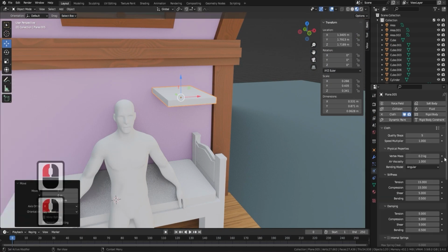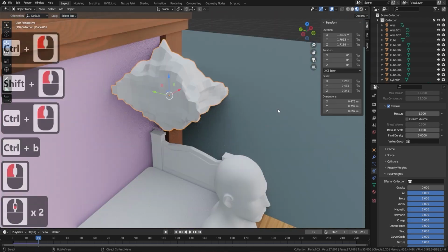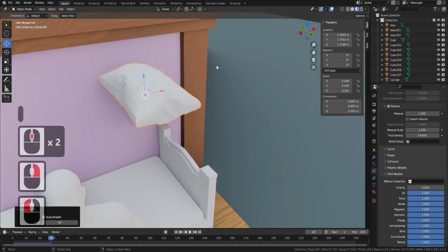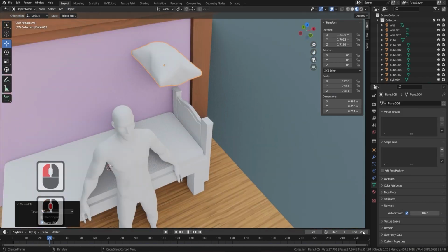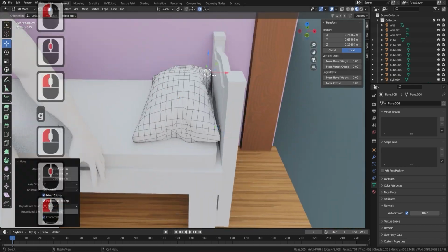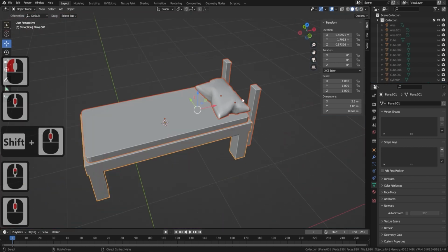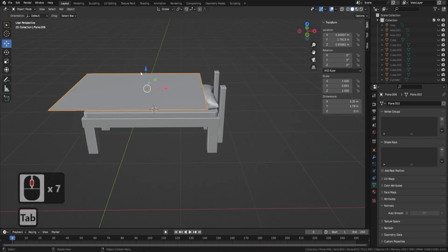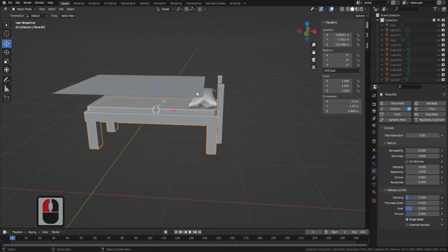Now you can see what I'm doing is I'm creating a pillow. I'm using the actual cloth generator, using the pressure on that, taking the gravity off, and then just expanding that pillow out. And we will be going into things like the particle system, things like the cloth simulator throughout the course. So you can see as well, we're going to use that for the actual sheet that drapes across the bed. It's just the easiest way to do it. You can of course go in and sculpt it, but again, it's all about increasing that actual workflow, making it as easy as possible.